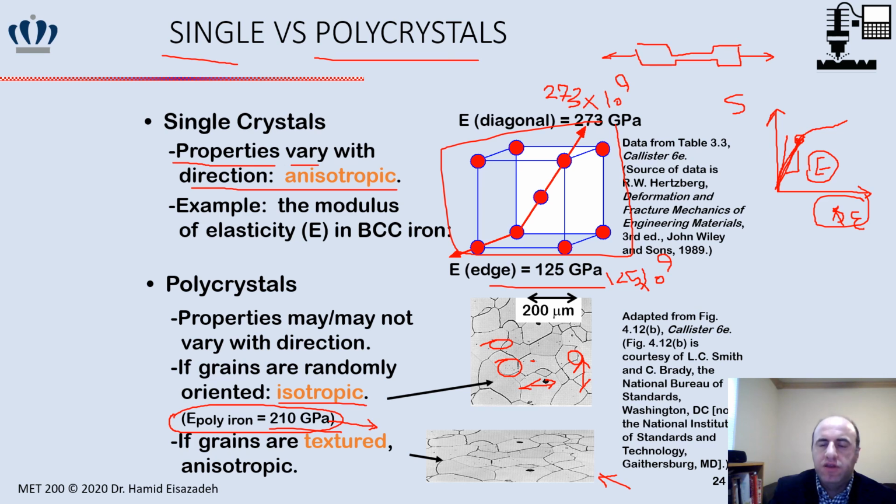The atoms or grains are going to be stretched along that direction, and it gives you an anisotropic property. So the size of the grains is different in different directions, right? This is important. Rolling is one of the manufacturing processes that changes the property, and you see anisotropic property.